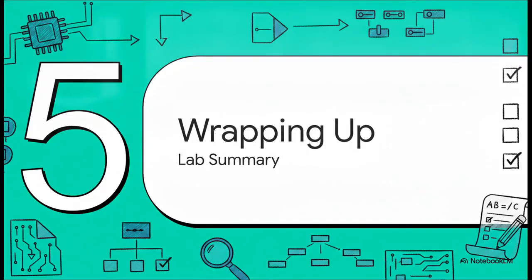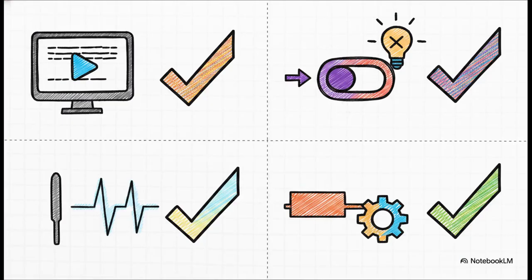All right, you made it. Let's wrap up this lab. To secure a win for Lab 4, just make sure your final submission clearly shows off these four compounding skills. First, prove you simulated that example code in Keil, routing P0 to P1. Second, document the code where you executed that bitwise XOR inversion. Third, grab a screenshot, probably from your simulated logic analyzer, showing your perfectly timed 1 kHz square wave on pin P2.2. And lastly, show off that steady 70% duty cycle PWM signal running on P2.5.